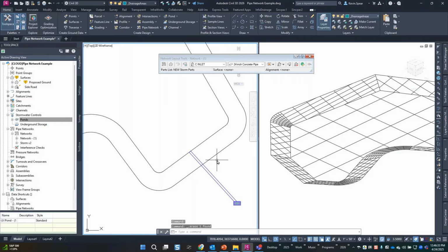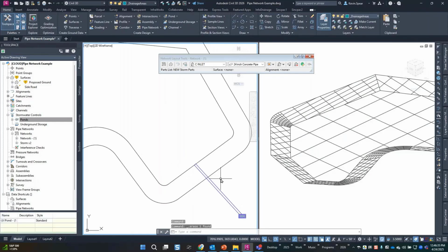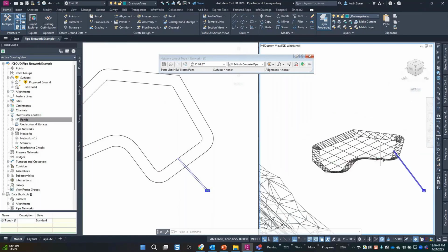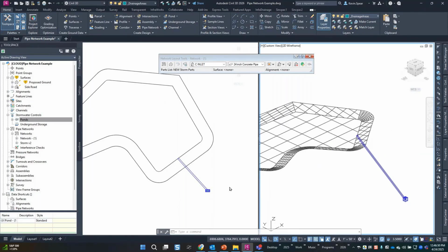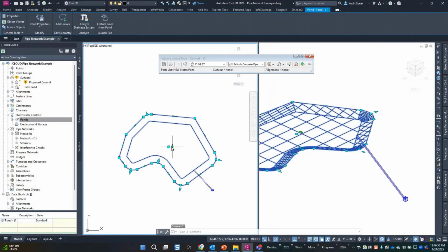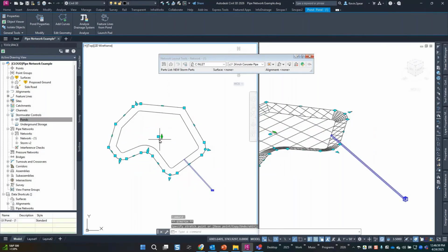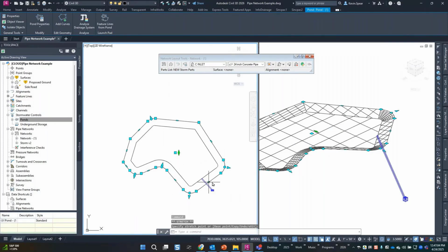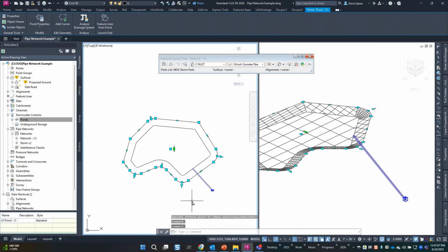So I guess I don't need that structure physically, just the end of the pipe. Not a flared end section, because a flared end section would still function as another structure. So what does that do? My elevations are clearly off, but that's okay. The idea is once you connect the pipe to the structure, in this case the pond, just like with a structure, that pipe goes along with it. So whatever happens to that side, it's going along for the ride.